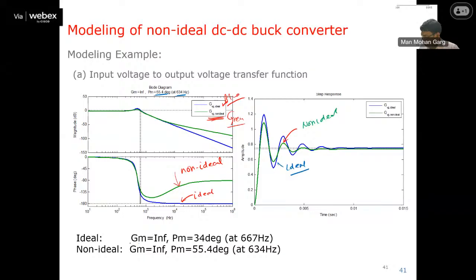Gain margin is infinite. What is this phase margin, gain margin? What is Bode plot in detail? We will discuss before the next class, before discussing the control system design. But for now, we know that for a system to be stable, its phase margin should be positive, its gain margin should be positive, right? And if phase margin is more, then the system will have less oscillations. And if its crossover frequency is more, then it will have less settling time. That much we need to know.